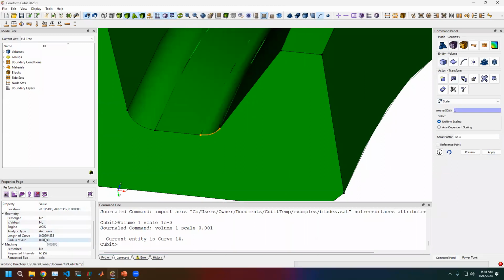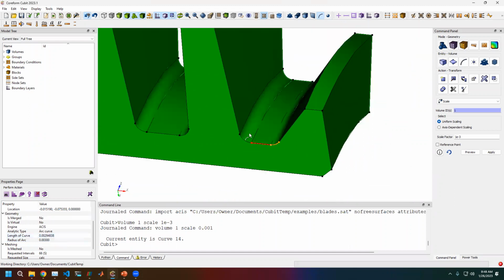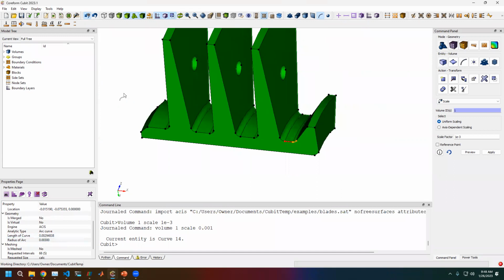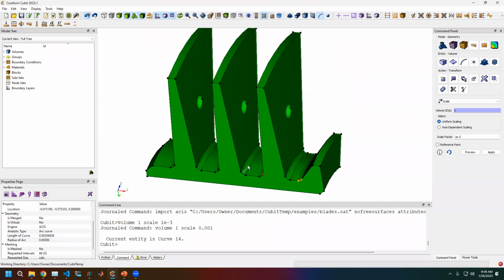So again, what that means is that as I do partitioning of my geometry for hex meshing, I've already used up several orders of magnitude of the absolute tolerance that I have available to me. Even if this might be units of meters, so maybe it's a 3 millimeter long part, what I would recommend doing is scale this model by the nearest power of 10 to get you up to around order 3.